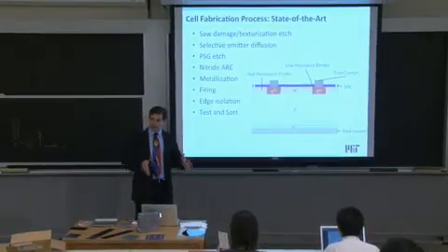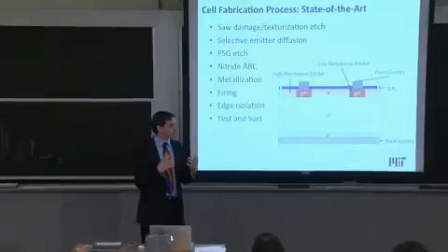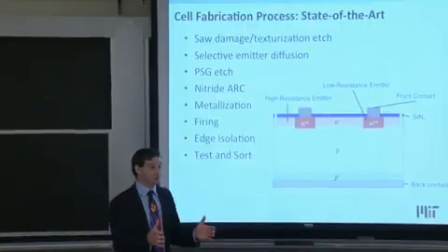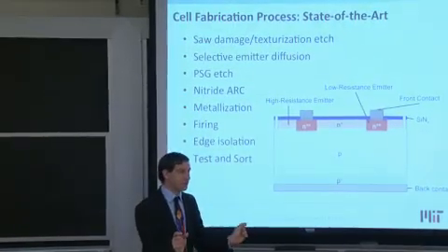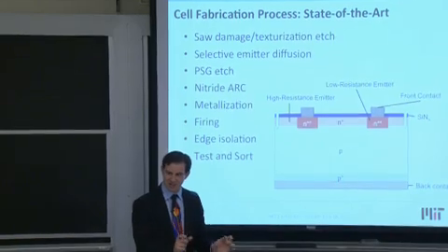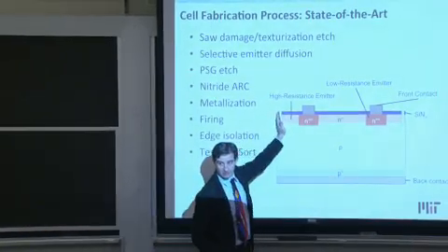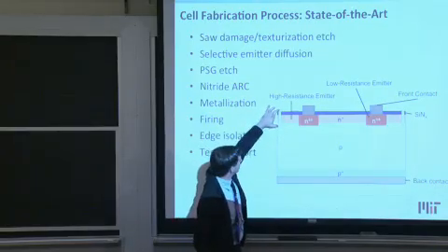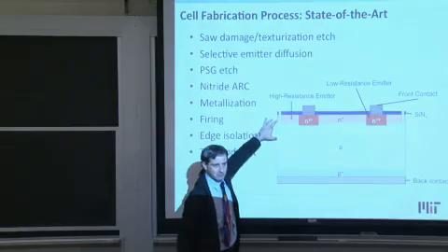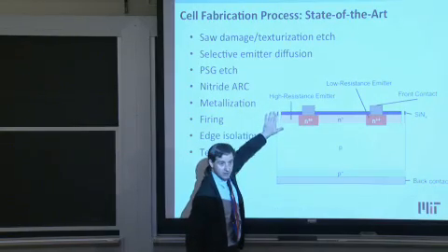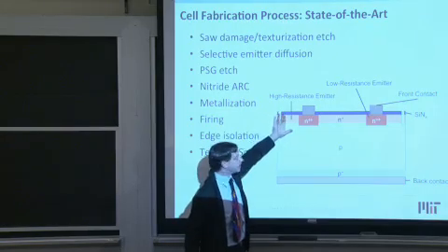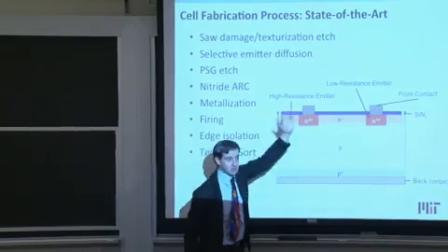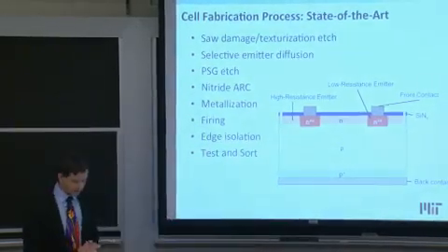Because you know your solar cell has a certain current density, let's say, milliamps per square centimeter. But if your area, your square centimeters, is smaller because you're cutting too far away from the edge, you're throwing away good material. This isn't a trench all the way through. It's just electrical isolation. So essentially, this material over here still exists. It's still hanging on to the device, but it's electrically isolated. This trench here is only about a couple of microns deep. And you're losing area. This area over here is not contributing to the photocurrent of your device. Any electron making it up into the emitter over here will just stay there and recombine eventually. It won't be able to be pulled out of the device.